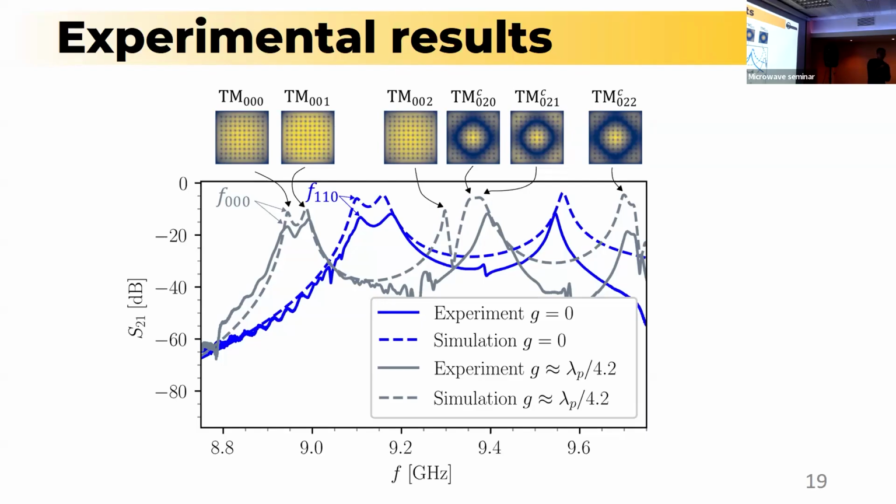The other detail is that directly we can see the field monitors from the simulations, and we can see that in the transversal section, this fundamental mode has a quasi-uniform field for this configuration. Here we also have side results about the higher order modes. All of them are transversal sections, and of course, these transversal sections are in regions in which we don't have nodes.